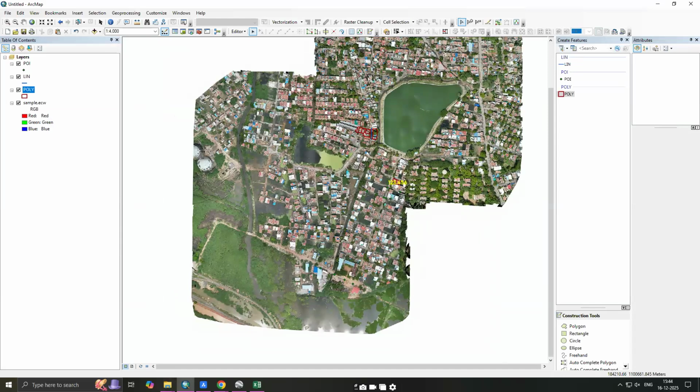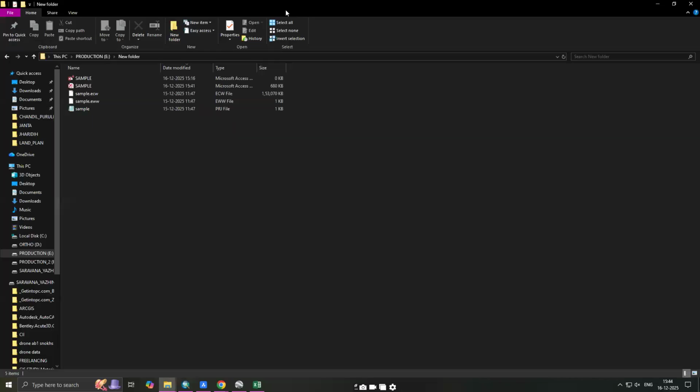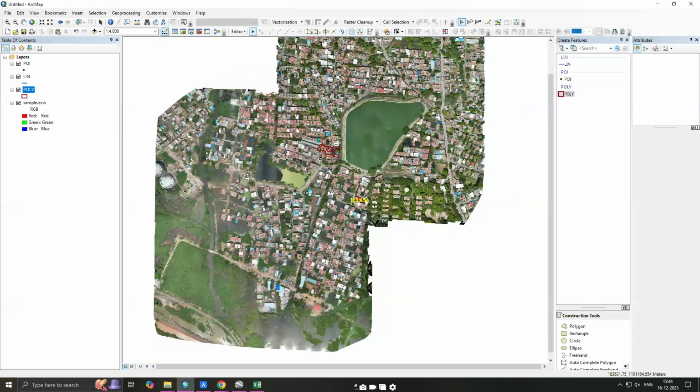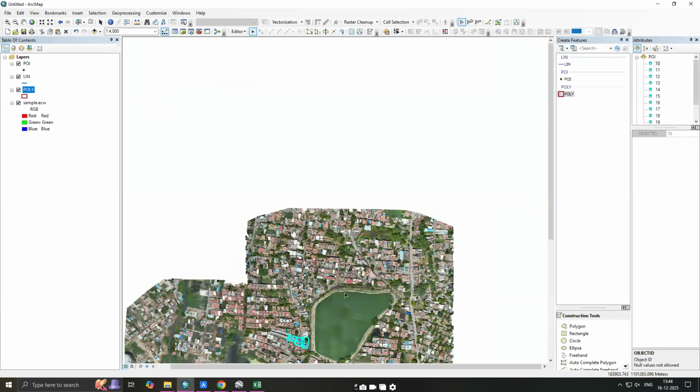See, if I'm creating a database, these two are the database files. Both will be from Microsoft Access itself. So you will not submit these databases because your company's every data will be present in a database. You will just export it into a shape file or something and deliver it so that they'll only have copies related to the actual data. They'll not have the shortcuts or tools or programming, whatever you're doing in the database. So whatever delivery we are doing in GIS, you have to export it into a shape file and only deliver that.